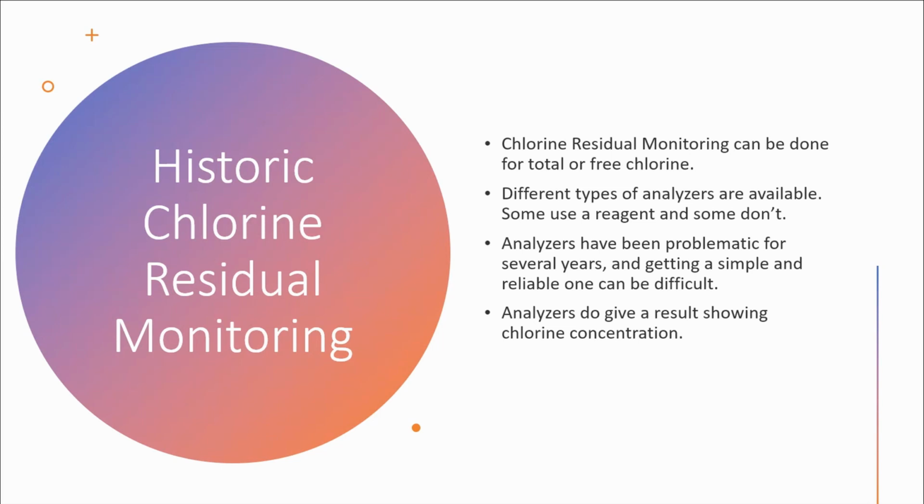I think another point with wastewater systems, and especially a lot of the operators in our area, is pH. Some of these lagoon systems will experience algae blooms that will spike the pH, and then your effective chlorine drops, and basically your disinfection ability. Obviously that one doesn't happen immediately, but it does happen within a fairly short, within a week period. And so being able to know and understand what's going on in a real-time manner is very beneficial.